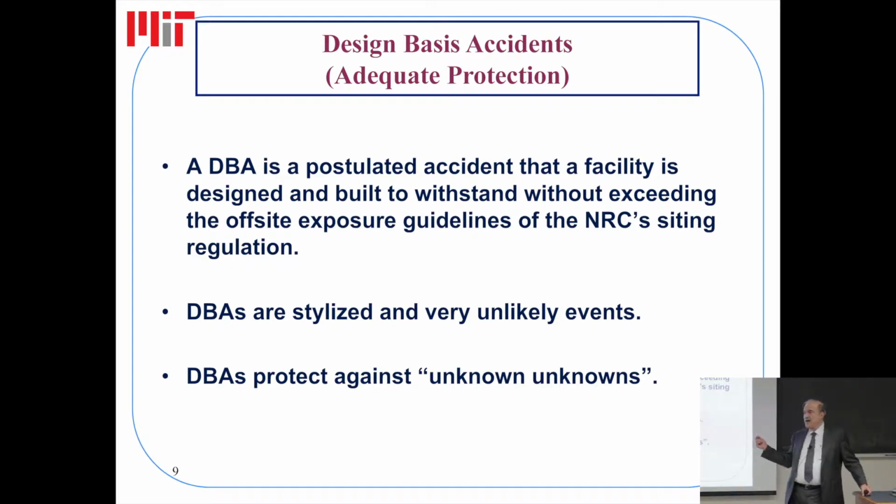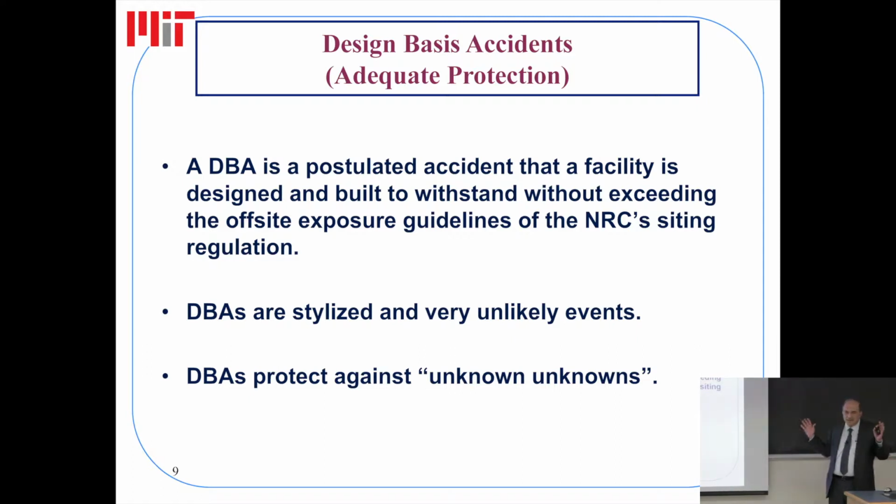And because of this large break LOCA DBA, the containment spray system is automatic. The operators cannot intervene. And what do you know? There have been 2 or 3 inadvertent actuations of the containment spray system, creating a mess in the containment, costing a lot of money to the utility and so on. But things are the way they are.